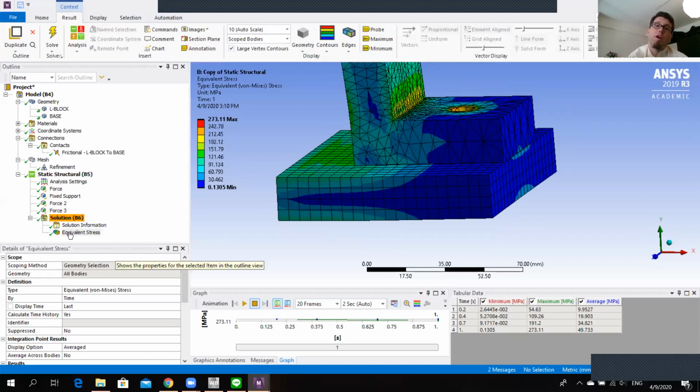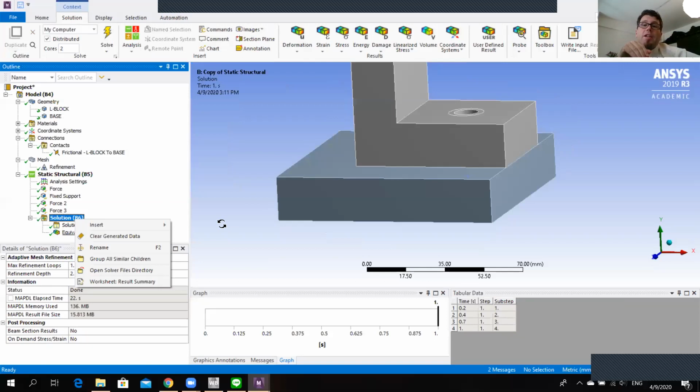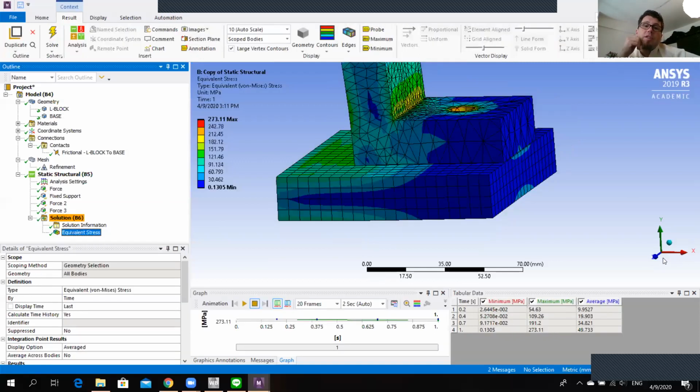Also, we don't worry too much about a separation of the two parts or a failure of the connection. What we're really looking at is the stress level in that corner, on that edge. So can you zoom us in on the stress results of that corner? I already checked it out. The nodes are just getting orange, so to speak.